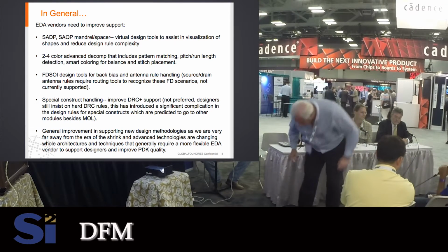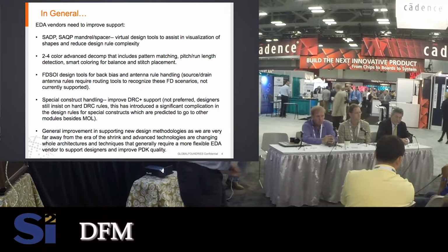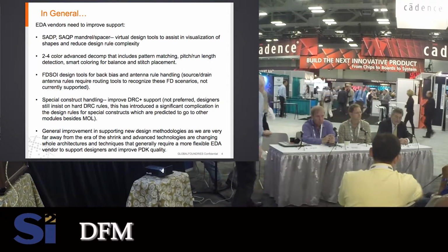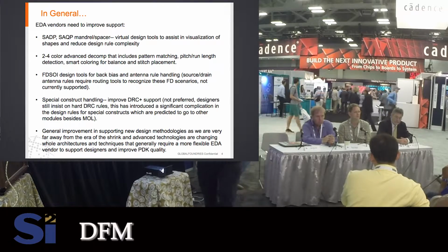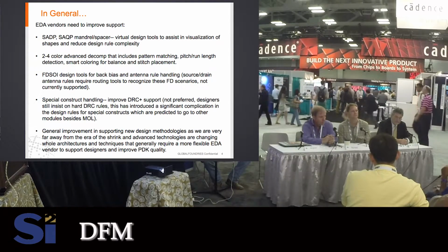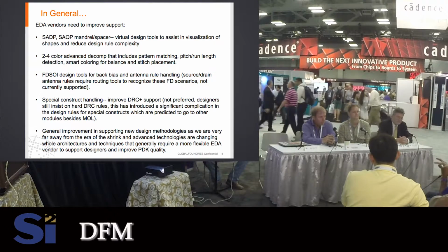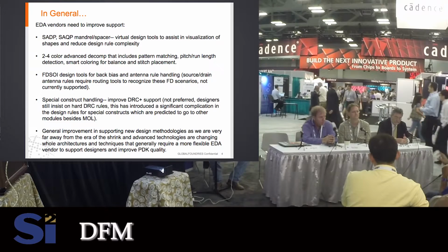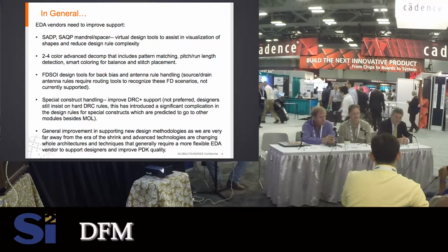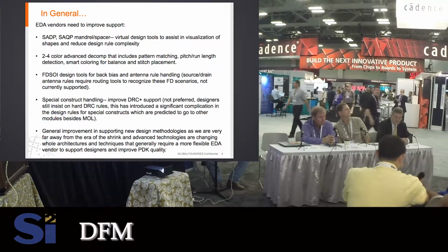My name is Asan Chaudhary. I'm from Samsung. Just a comment, I think it will come through the deck for the designer. The fab DRC will automatically put those rules there. Correct. So if you run your DRC, and if you put the marker as you mentioned, it should catch that if you violate the spacing between the two nets which have different voltage. Right, that is designed by the fab process engineers. Thank you. Thanks.